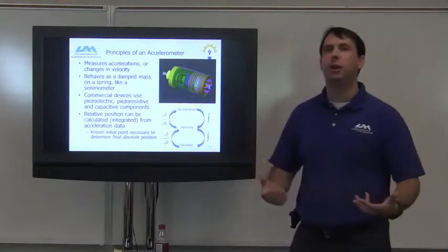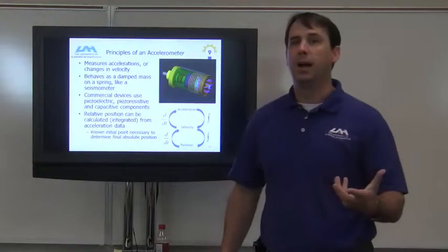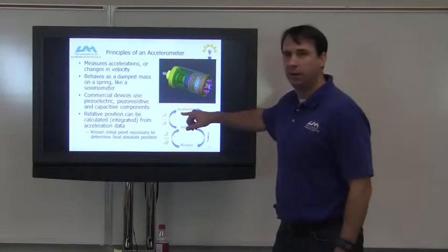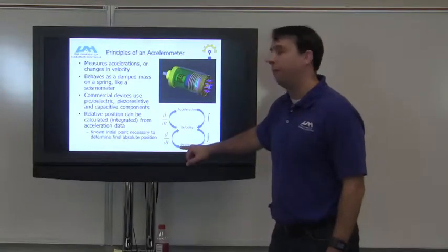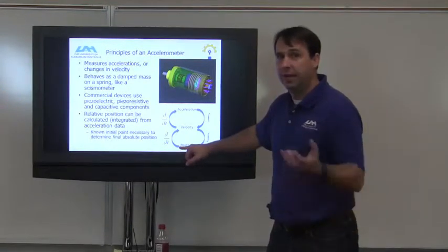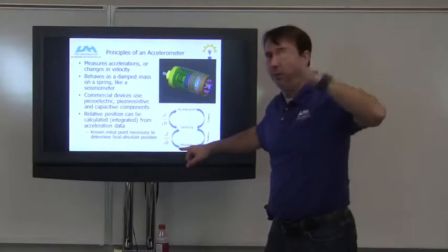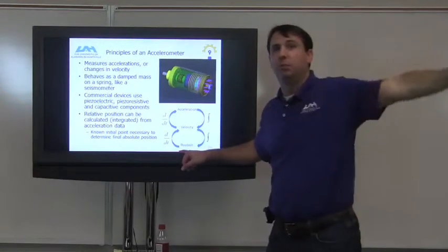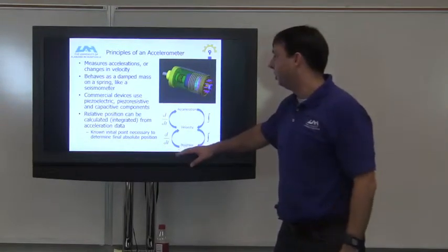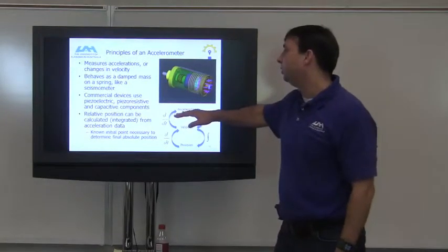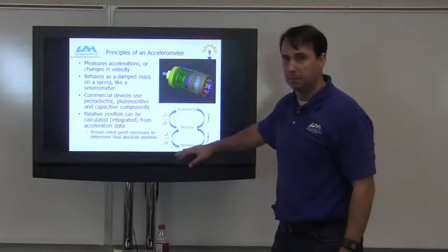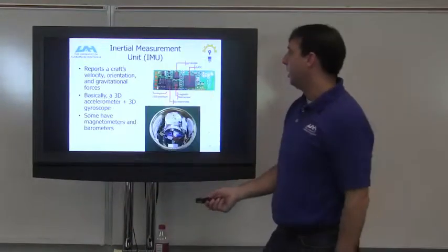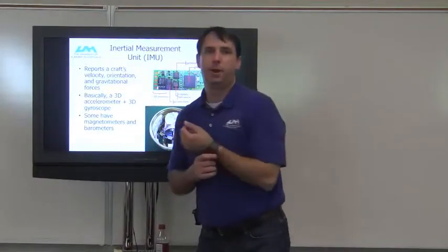So there's a relationship there that we can exploit, because an accelerometer measures accelerations, but from that you can determine how far something moved, how much it moved. And that's a vibration measurement, right? That's what you want to measure for internal structure. That's also what you want to measure for wind speed, is how much something moved. So the positional measurements are what you're looking for. We just use accelerometers to take positional measurements. Does that make sense?